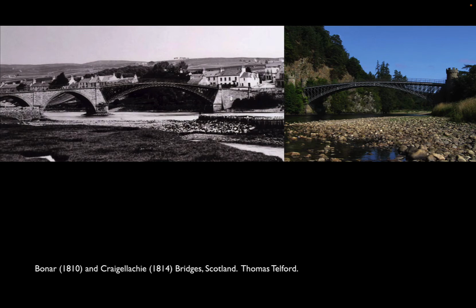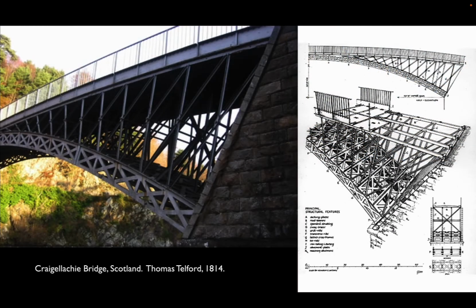A new sense of scale, a new sense of proportion, a new sense of what we might think of as structural finesse almost. And here in detail, you can see that the arch is very clearly cast iron. The web is wrought iron. Those are rolled angles that are connecting the deck and the arch. And remember, wrought iron is reliable in tension in ways that cast iron is not. So the web is doing the work of connecting the two. It's able to take both compression and tension and make the deck and the arch behave together, and to do this with a remarkably small amount of material.